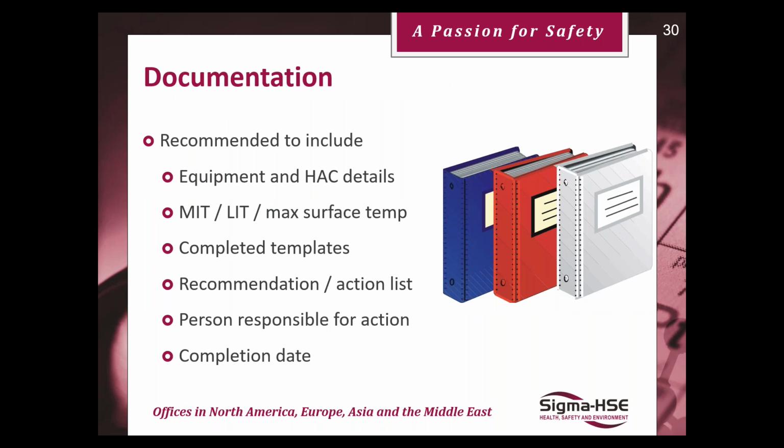So again, as I mentioned, for documentation, you need to know the hazardous zones, the flammability data, and the completed templates. This is the risk assessment tables. Action list, responsible for the action. So these are the recommendations that come out of it, as you would in any risk assessment.